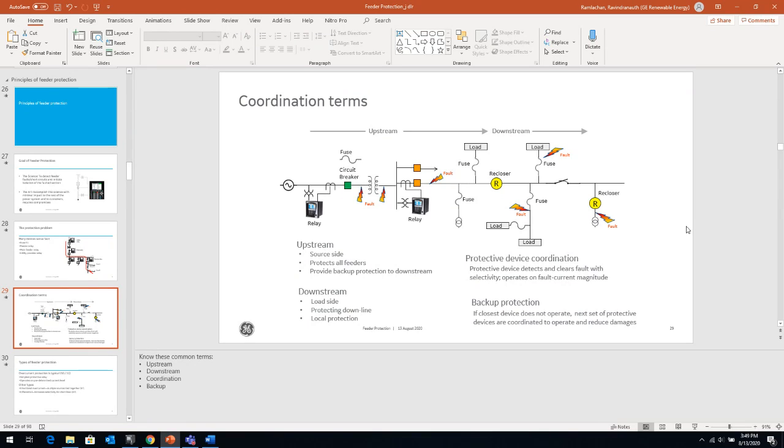On the breakers out of a substation, I've seen a 2 second and then maybe a longer 5 second, kind of doing away with the 0.3, because on a distribution line that quick reclose really doesn't buy you anything.